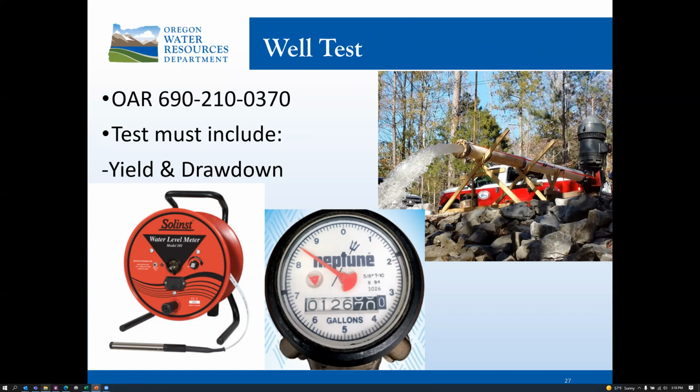That being said, most people who operate air rotary equipment are not going to be able to accurately record their drawdown. And that brings up the statement I just said, that any testing method that does not provide for drawdown measurements during testing is not an accurate or reliable test of yield. The water that is returned to the surface through an air test, because of how it evacuates the majority of that water via air, is very hard to document drawdown, or it will document that all the water was evacuated from the well. So again, we're getting a distorted view of yield and not an accurate representation of that well's yield over time. Again, when we're looking at the requirements of the well test, yield and drawdown are those requirements, and that is the emphasis of this slide.